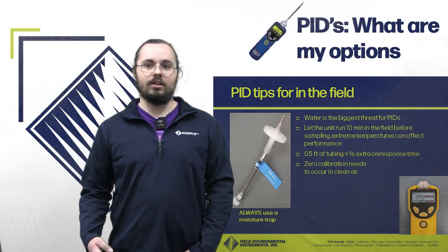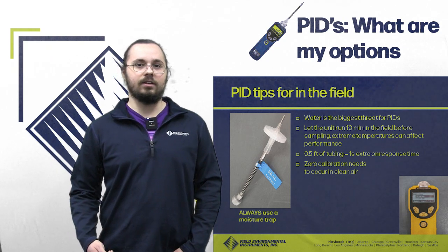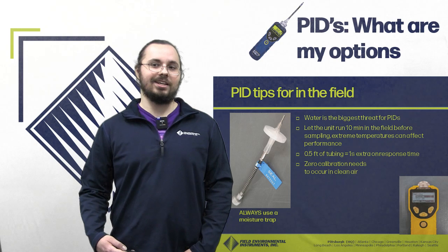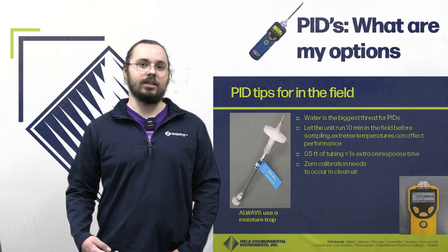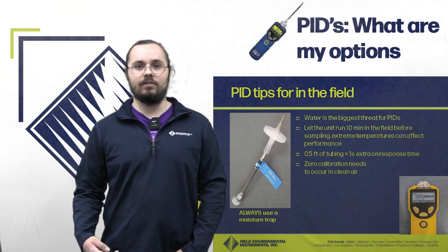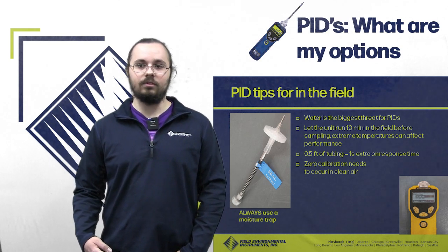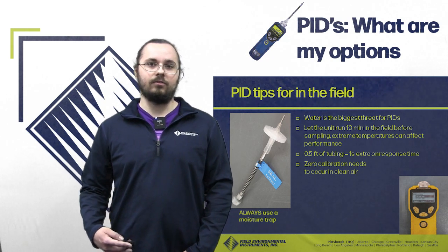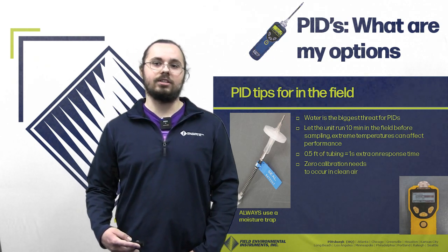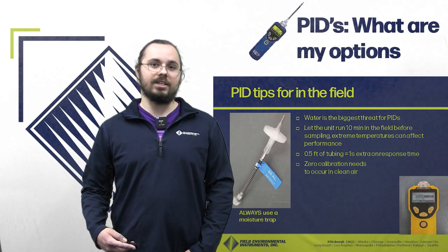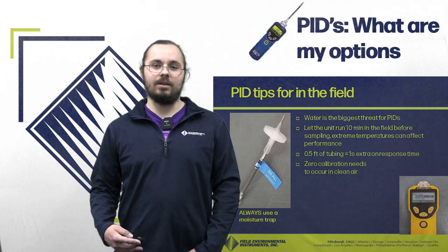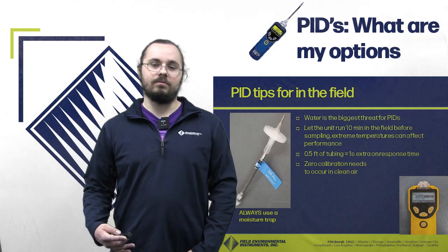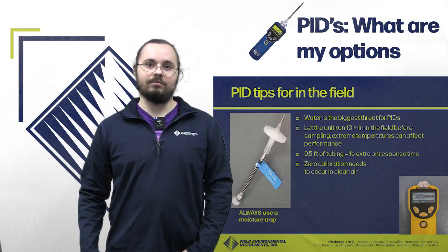Another thing to note is if you're using tubing on the unit to get a sample from farther away, every half foot of tubing adds 1 second extra response time to your reading. So be sure to account for that whenever you're doing that. Also remember, always do your zero calibration before you go out and take your samples. Make sure you do this in a clean air environment, typically anywhere outside where you know there's no contaminants, or anywhere else like that.